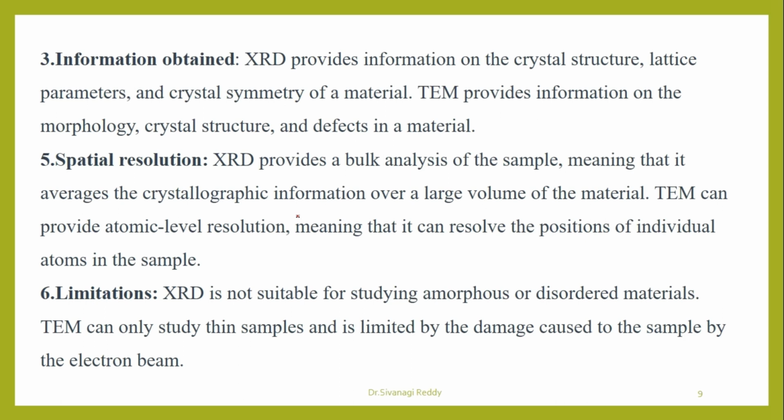Then the information we will get: crystal structure, lattice parameters and crystal symmetry from XRD. TEM will provide information on morphology, crystal structure, defects in the materials. Then when we come to the resolution, it is comparatively less for XRD, and for TEM it is atomic level resolution.